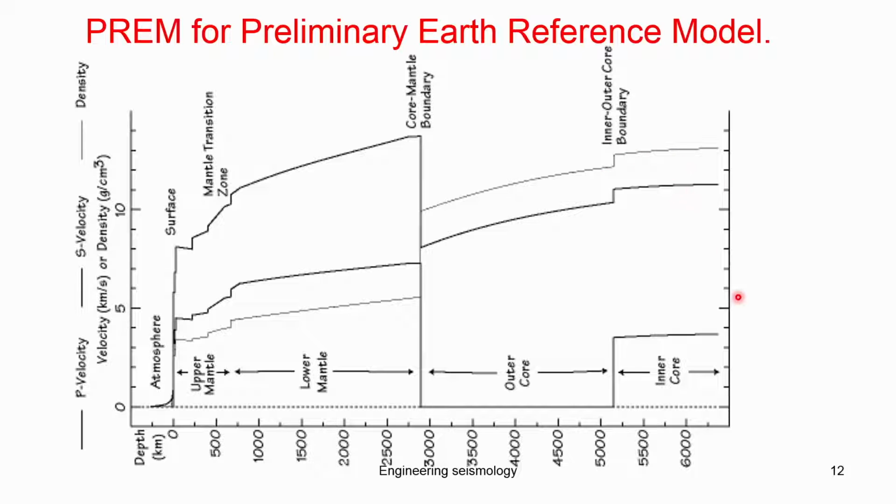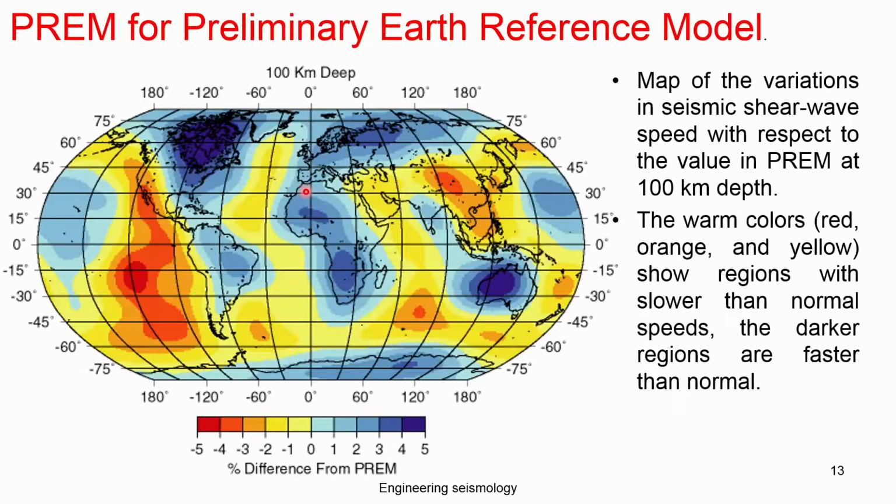Then, followed by the opposite side, if you go, you will get these recordings once again. So, this helps give the average velocity of that particular location. These velocities again change from place to place. If I measure this velocity in the Bangalore region, it will be different. If I measure the same thing in the Delhi region, it will be different because of the composition of the material. As the wave properties are controlled by the constrained modulus, shear modulus and density, when the material changes, your velocity also changes. So, that one has to remember.